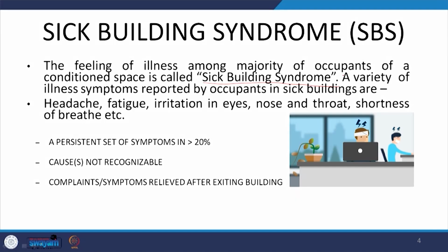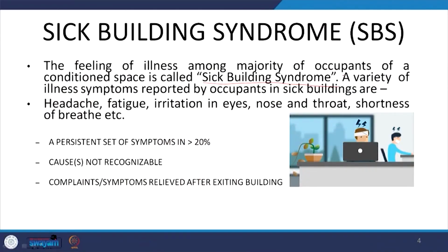Now, how do we define that a building has sick building syndrome? Where there is a persistent set of symptoms in more than 20% of the occupants, and the causes for those symptoms are not recognizable. Somebody might be having a nose and throat infection for a particular reason, maybe there was a flu.